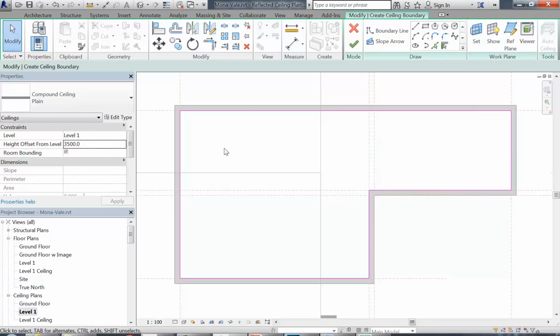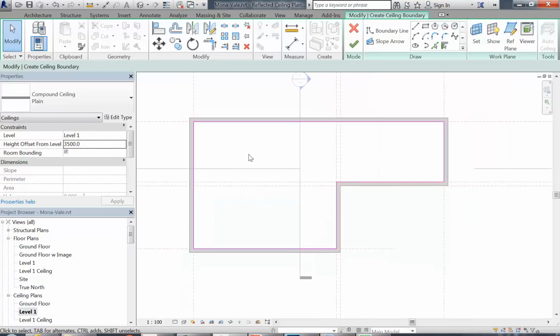How do you know once you've created one? You'll have a look in your section. Usually is the best way to see it. It's hard to see in your floor plan, in your ceiling plan even. How do you have the second version? With the level tool. So it should be from the floor. Yes. If a part of the ceiling is a bulkhead, you have to do the ceiling bulkhead separately. That's right. So you may have a couple of ceilings, or you might model in extra to make the ceiling thicker at a certain point. A couple of ways of doing it, but yeah, usually you need to do more. Do ceiling first, and then later you do the bulkhead. Exactly. Yeah, that will be underneath the ceiling.